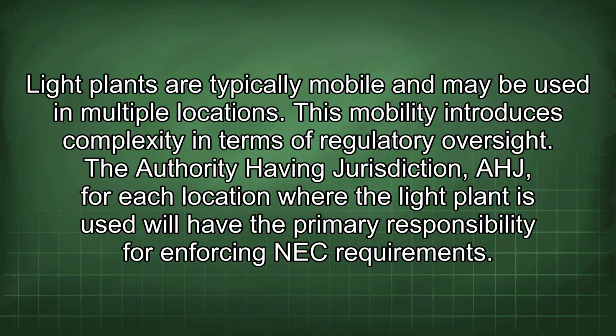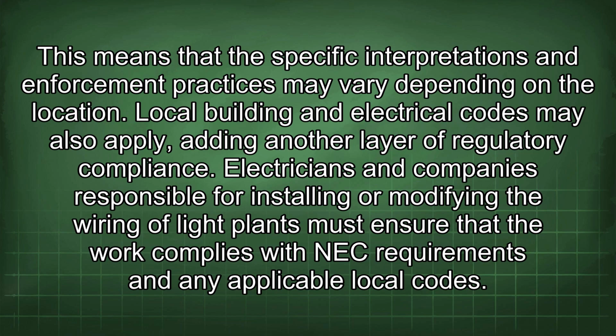Light plants are typically mobile and may be used in multiple locations. This mobility introduces complexity in terms of regulatory oversight. The authority having jurisdiction, AHJ, for each location where the light plant is used will have the primary responsibility for enforcing NEC requirements. This means that the specific interpretations and enforcement practices may vary depending on the location. Local building and electrical codes may also apply, adding another layer of regulatory compliance.